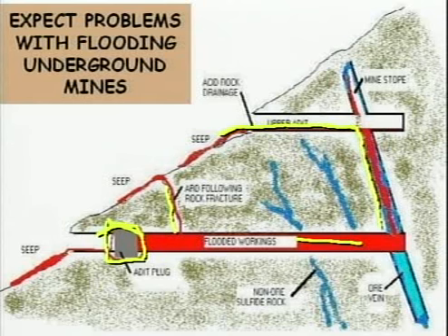The plug site also needs to be carefully considered. The geostatic head, which is the distance above the plug to the ground surface, needs to be greater than the anticipated hydrostatic head, which is the head on the mine pool itself, behind the plug, or hydrofracturing will occur and the plug could fail. Indeed, mine flooding is a mitigation option that should not be approached lightly.